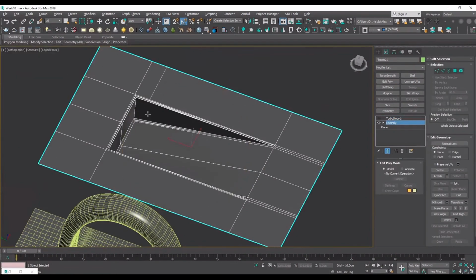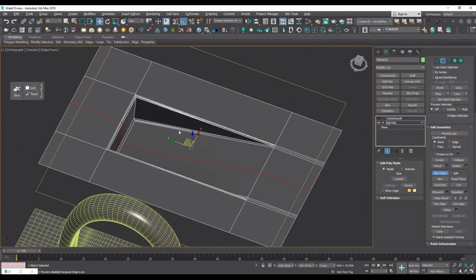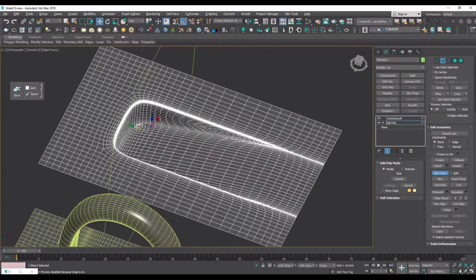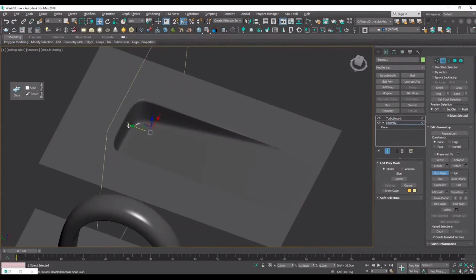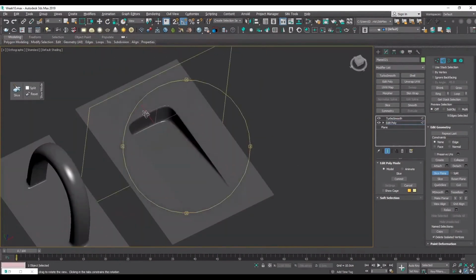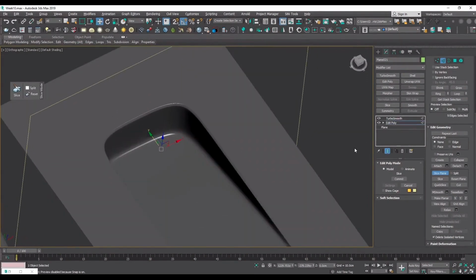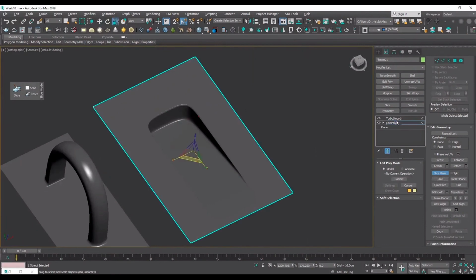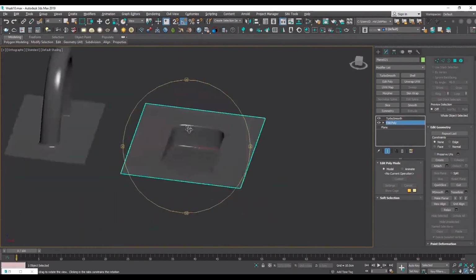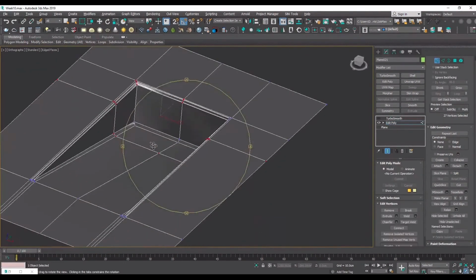Again, I pick up my slice plane tool to demonstrate how adding a new edge loop to the mesh affects the sharpness of the corners and the curvature that they produce. If you move them closer, you will see it narrows down, and if you move it away, it results in more roundness here. So now I confirm the slice, and there's the shape we want.